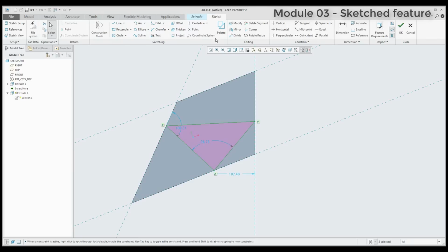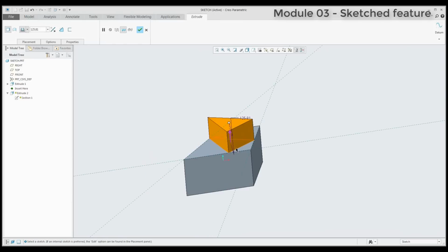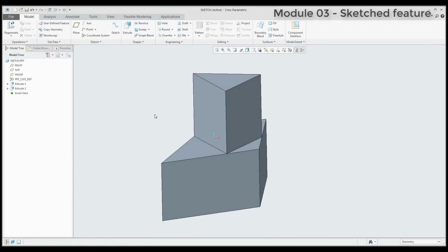And what about the other features? I will go straight on and create another feature, so we can add other objects, for example extrude, and continue. If I create the extrude feature and go straight on, you can see here that we would like to create, for example, for this extrude feature directly in the sketch, the axis.